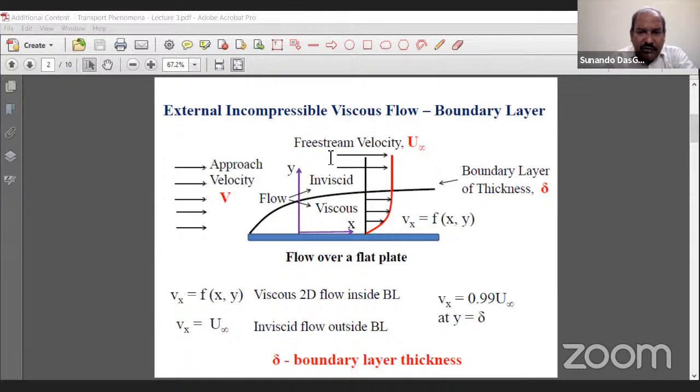The velocity head on one side and the velocity head on the other side are going to be different because it's a curved surface, and hence the flow area available to the fluid is going to be different. So there would be a pressure gradient which can be defined in terms of Bernoulli's equation, and that's the special case of flow over a curved plate.